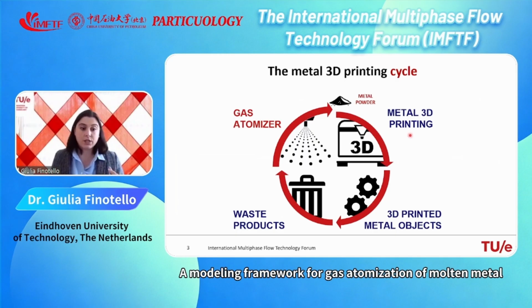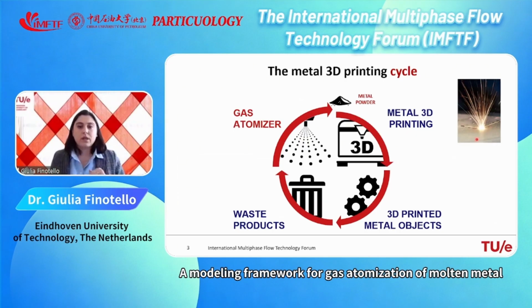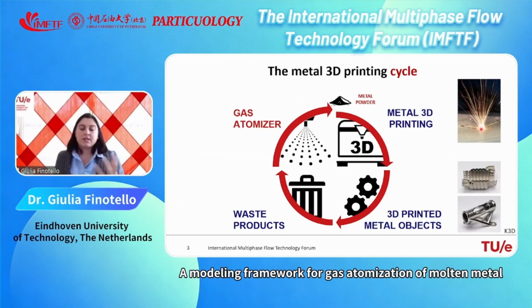It is used in a layer of powder, on which a laser beam or an energy source acts. These powders are melted locally, so that only part is melted, and then layer by layer the 3D printed object can be manufactured. What you obtain as a result is this example of a 3D printed object.